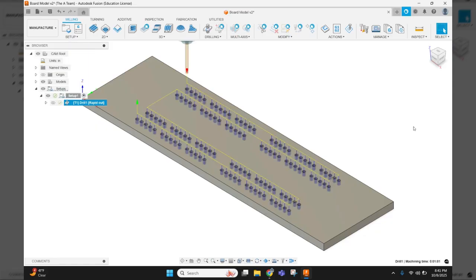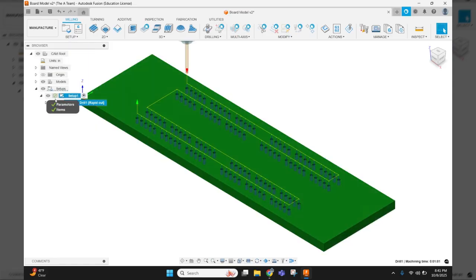and we are in the process of creating a tool path. So you can see my wheels over here spun for a minute. Now I've got a tool path here. So this object on my screen represents the drill bit. You can kind of see the tool holder up above here, that little bit of blue. The yellow line is where it's going to travel from hole to hole, and the blue line is where it's going to do its drilling. So as I look here, I can see that the whole thing is selected. It looks like it's hitting all the holes. I think that's good.